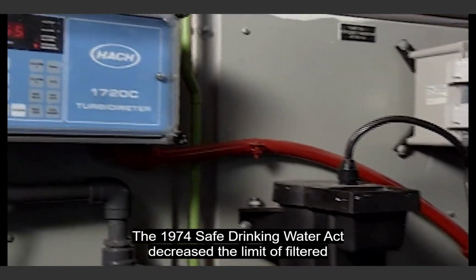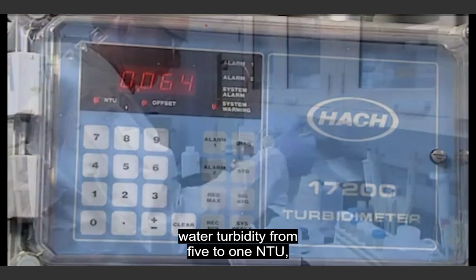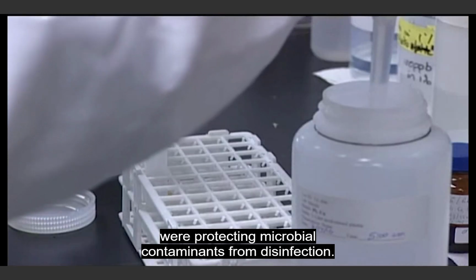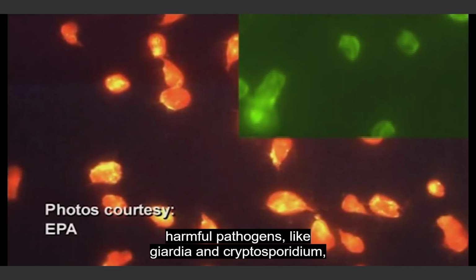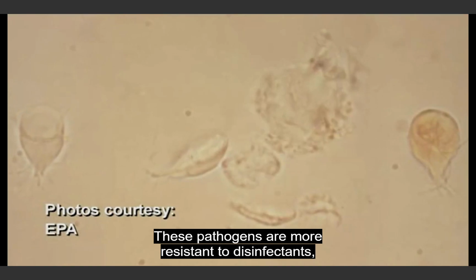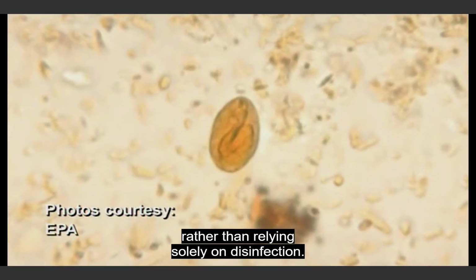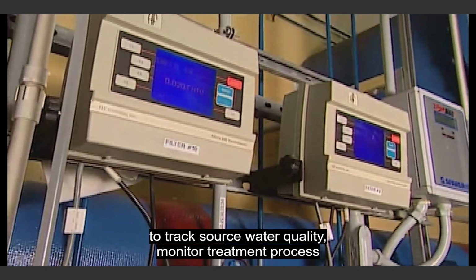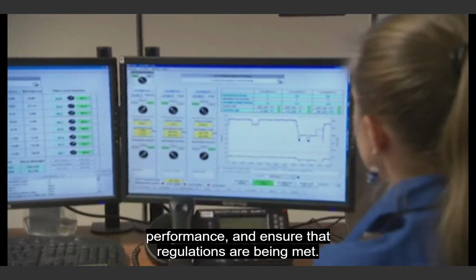The 1974 Safe Drinking Water Act decreased the limit of filtered water turbidity from 5 to 1 NTU when researchers discovered particles causing turbidity were protecting microbial contaminants from disinfection. The regulation is designed to ensure harmful pathogens like Giardia and Cryptosporidium are removed from drinking water. These pathogens are more resistant to disinfectants, so it is necessary to physically remove them from the water rather than relying solely on disinfection. Turbidimeters have long been used in water utilities to track source water quality, monitor treatment process performance, and ensure that regulations are being met.